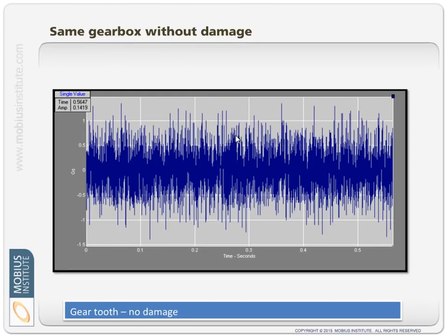Gosh, I'm confused. Time waveform analysis is too hard. And that is a conclusion that a lot of people come to. The fact is, simplifying the story, if I look at a time waveform like that, then 2 seconds later I can move on to the next bit of data, because the time waveform isn't really telling me anything that I wouldn't be able to pick up out of the spectrum. The spectrum translates all of that into useful information.